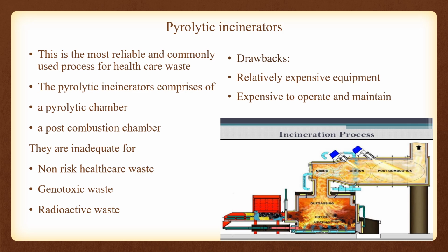The activities involved in the operation of pyrolytic incinerators are: removal of the ashes left inside the pyrolytic chamber, loading the waste packages to be incinerated, ignition of the pyrolytic fuel burner to start waste burning in the pyrolytic chamber, ignition of the fuel burner in the post combustion chamber, monitoring of the high temperature burning of gas inside the post combustion chamber, and stopping the fuel burners after completion of the waste and gas burning and letting the incinerator cool. These are the different activities in the functioning of pyrolytic incinerators.